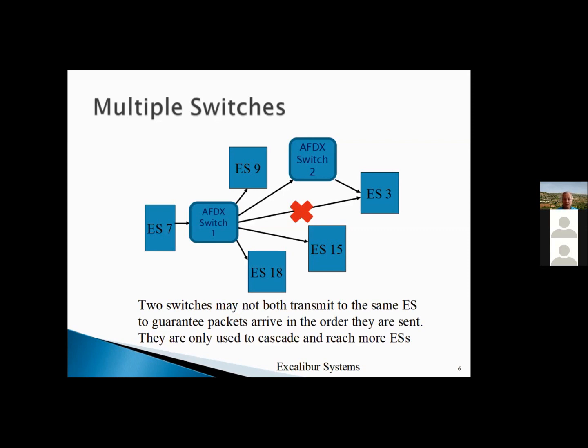As opposed to if your only switch was in the cockpit, then you need to draw multiple wires from the switch to each wing. And that's a lot of weight. Whereas if I put the switch at the beginning of the wing, I only need one wire going from the cockpit to the wing, and then I have multiple wires going the shorter distances on the wing. So that's just an example, obviously. So you're going to make this decision based on how you can limit your wiring and yet not have too complex a network.